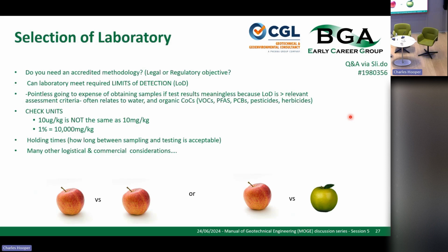Do you need to know whether that test is accredited? Does it need to be UKAS or MCERTS? They're both UK accreditations. If you have a legal or regulatory objective, I would say yes, your sample does need to. Not all labs test all things to accredited methods. It is not the lab that is accredited, it is the individual test. So really check the lab's accreditations. You may find that they have accreditations for metals, some organics, some TPH, but they don't have it for all.